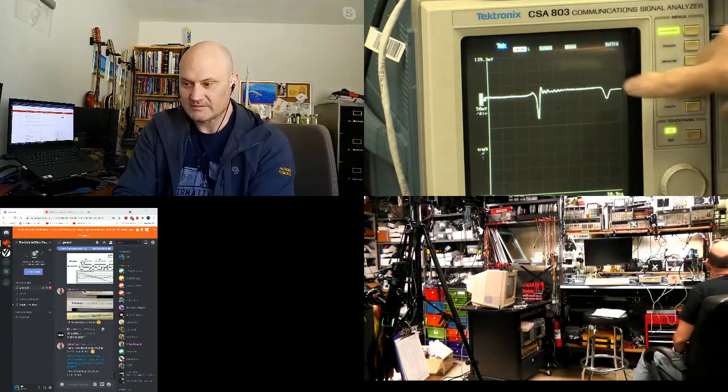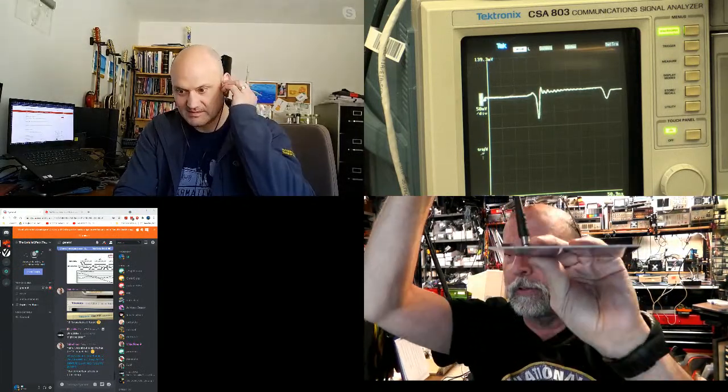And then it hits the terminator. Well, we see that the terminator isn't nearly as big a spike, so that tells me that the PC board and the connector are not a big discontinuity. They are some, but it's really the cable that caused the big spike. This soldered cable connector, it's not hand soldered, I'm sure, where it goes to the board is what's causing that first negative spike. Now, I happen to like that negative spike because that tells me without doubt where the cable ends and where my PC board starts.